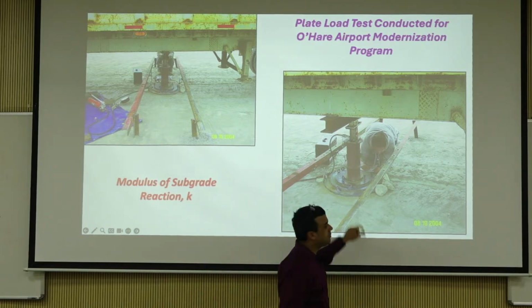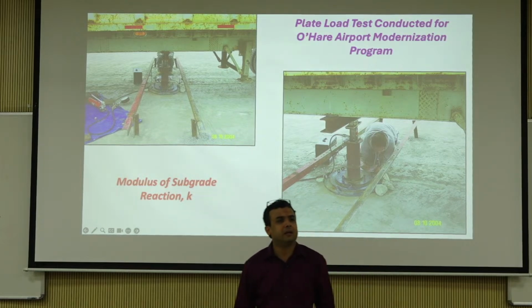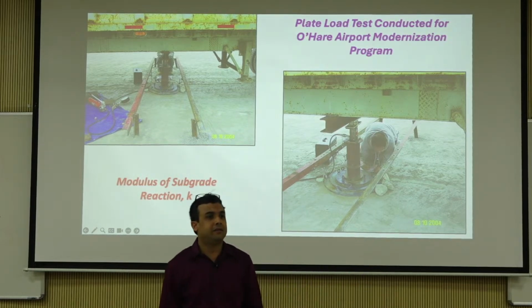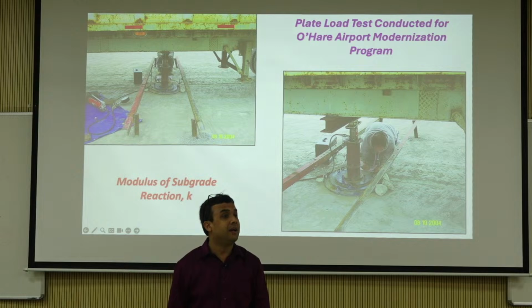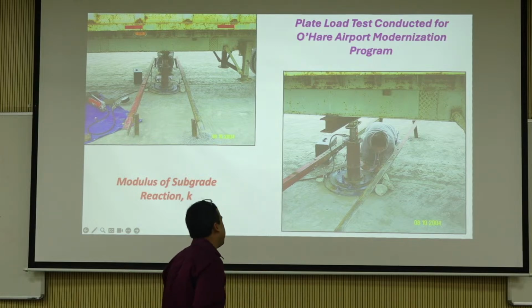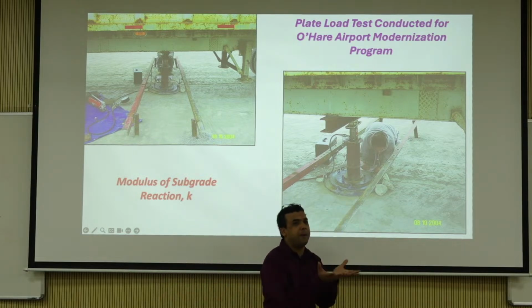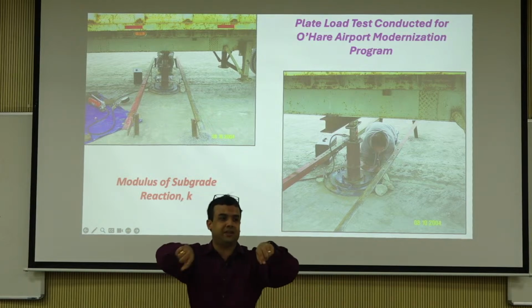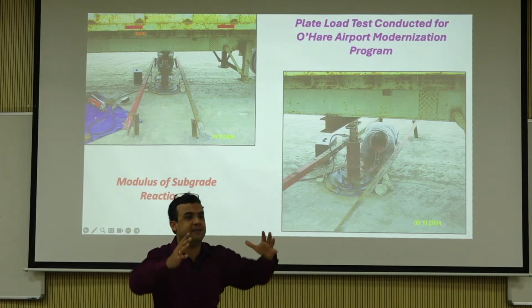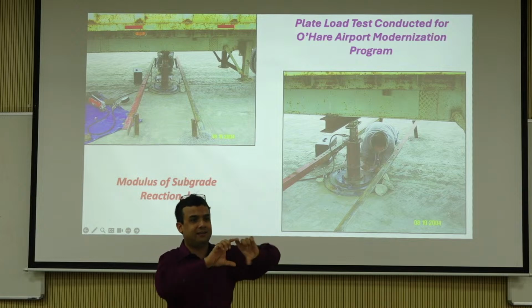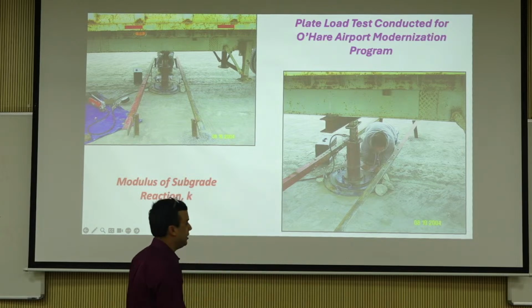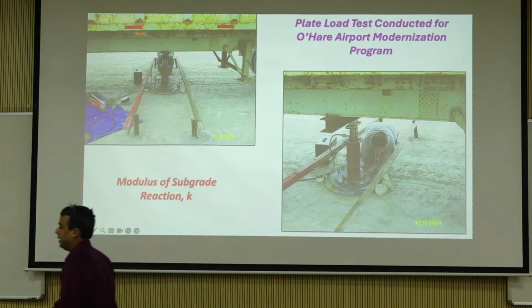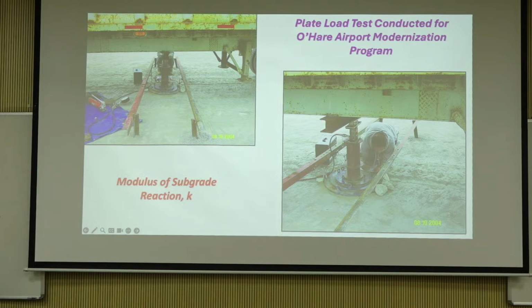Why can't you just use one plate? Well, related. You are actually trying to avoid bending of the plates because we are trying to measure the deflections at the circumference, right? So the plate actually sometimes bends as well. So if you make it thicker, the bending stiffness actually increases. So it's actually to avoid errors.